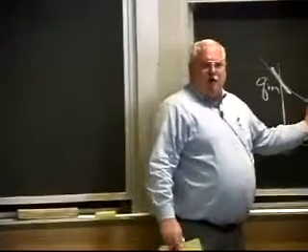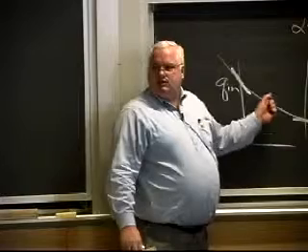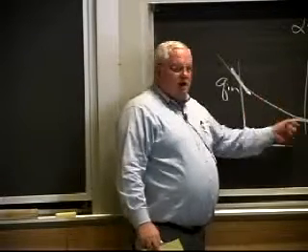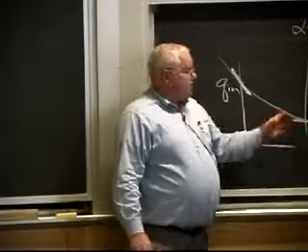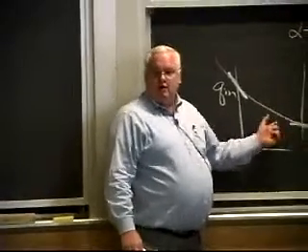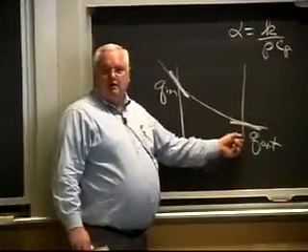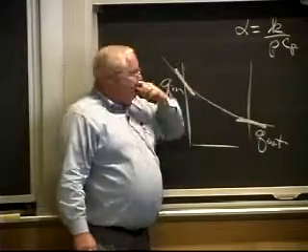If I want to know how fast the heat accumulates, I need to know rho C sub P, the heat capacity of this thing, times the difference between these two, right? Will it accumulate here or not? Which one's larger? Q in or Q out? Q in is larger, so the heat accumulates and this thing heats up.